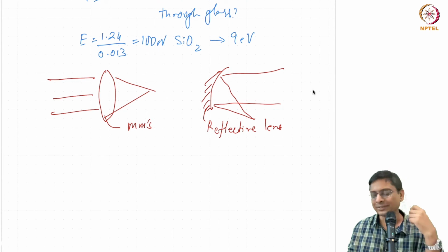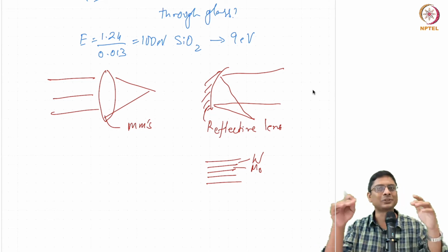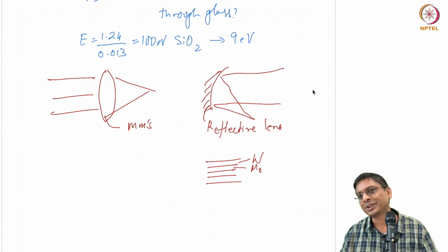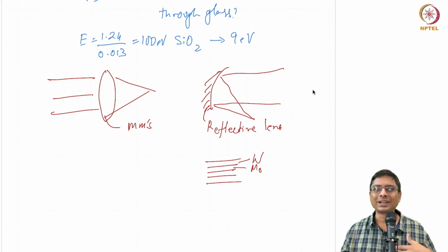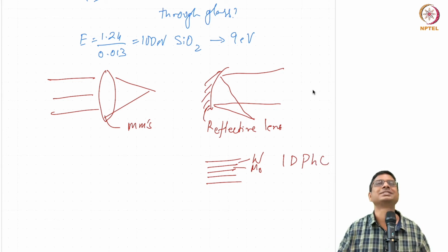I talked about it multiple times. Anyway, multiple layers. Tungsten and, I think, molybdenum. You make thin films of tungsten and molybdenum in a periodic fashion, like a 1D photonic crystal. You make the reflectivity go very high. Why tungsten and molybdenum? They're very, very hard, so they're not getting damaged. So you make a metal thin film out of it. You make a reflective film, 1D photonic crystal, 1D PHC, right? You make a photonic crystal out of it and then you reflect light. At that wavelength, it cannot penetrate because it simply has a band gap.